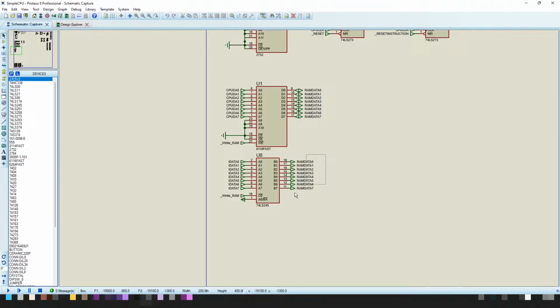So what this means is that when the RAM is not being written to, we isolate the internal RAM data values from the internal data. So we're able to pull out that information separately if we want to. But when we're writing it, we want to pass through the data that we expect to see from the internal data bus to the RAM. We present it to the RAM. The RAM will then remember it only when this signal is being held low here.